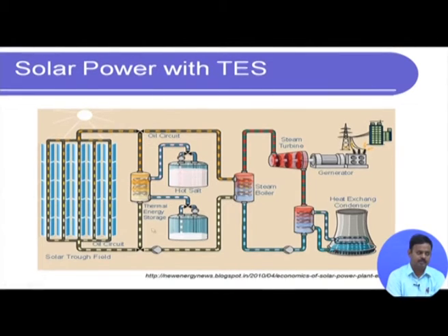during night time or during a cloudy day. The oil will move up like this and gain heat from this heated molten salt, and then the cooled down salt will accumulate in the lower reservoir. The heated oil then will go through this circuit, go to the boiler, generate steam so that the power generation is maintained, and then come back and just complete the loop like this, clear.